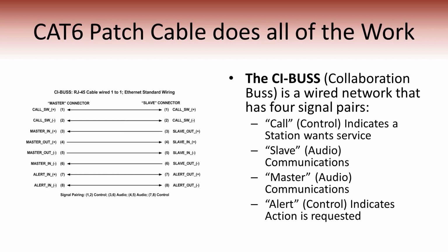If for some reason you need 2 inputs and you don't need an output, you can use a master output as a slave input. What you have to do is build a custom Cat5 cable that crosses these pairs over. That's all you got to do. Swap those pairs, an input can become an output. The system doesn't know the difference. It's set up to be convenient for your technician.